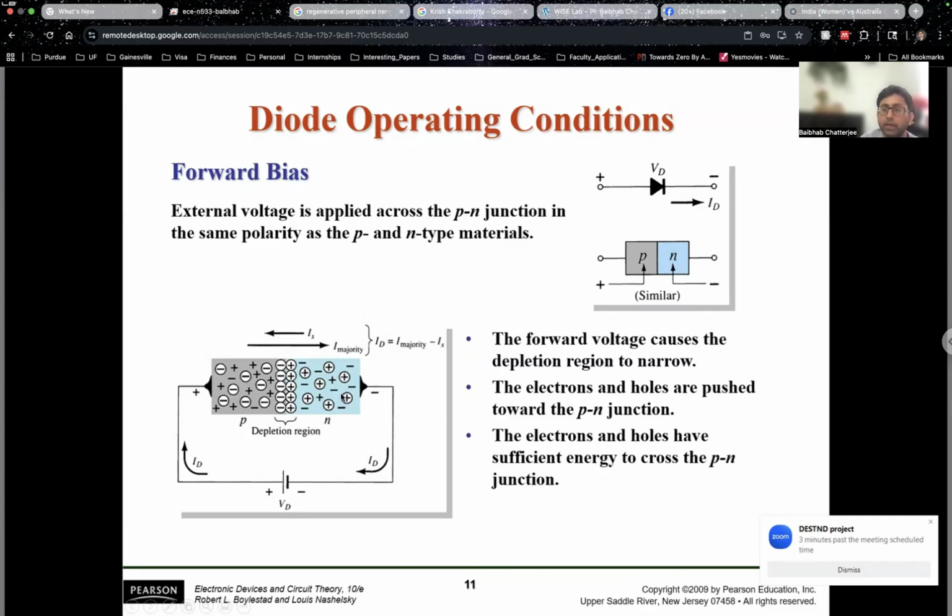But why it happens, again, that should be explained very well in a device physics class or a semiconductor physics class, that why do they have these excess electrons? And that's simply because, let's say, if you dope it with a phosphorus atom, phosphorus has one additional conduction band or outer shell electron, which can move around. And that creates those excess of electrons for the n-type. P-type, again, you're doping it with, for example, boron, and boron has one less electron. So you're creating an absence of electron, which is the hole.